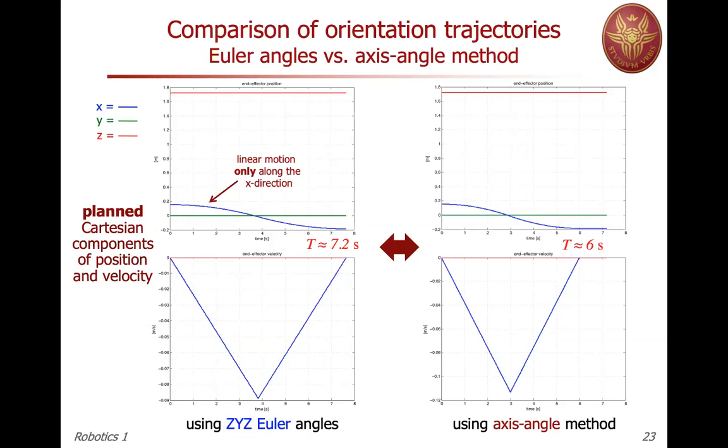And in fact, we find out, because of these plots, we can retrospectively say that we were not able to reach the maximum speed because before reaching the maximum speed, we decelerate. So this is a subclass of the trapezoidal speed profile, which collapses into a triangular profile.